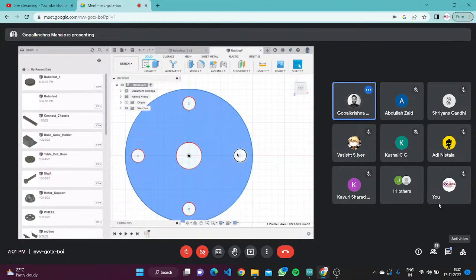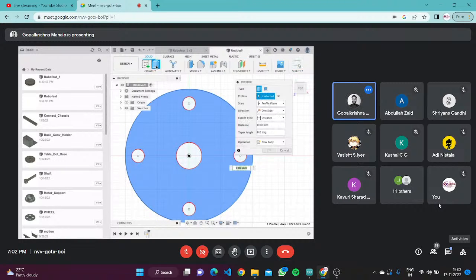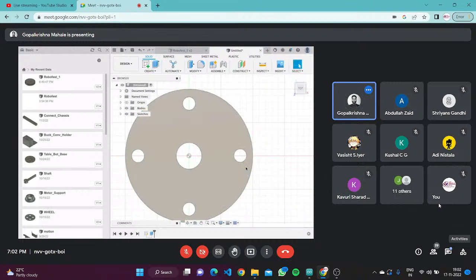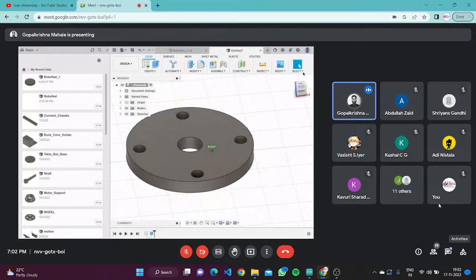I want to keep these hollow, because they are the mounting holes for the spacers. I've selected this, hit extrude, and you'll get this window. Type anything, for example, I'll type in 10. The unit we are using throughout the workshop is millimeters. Hit enter, and you have this.